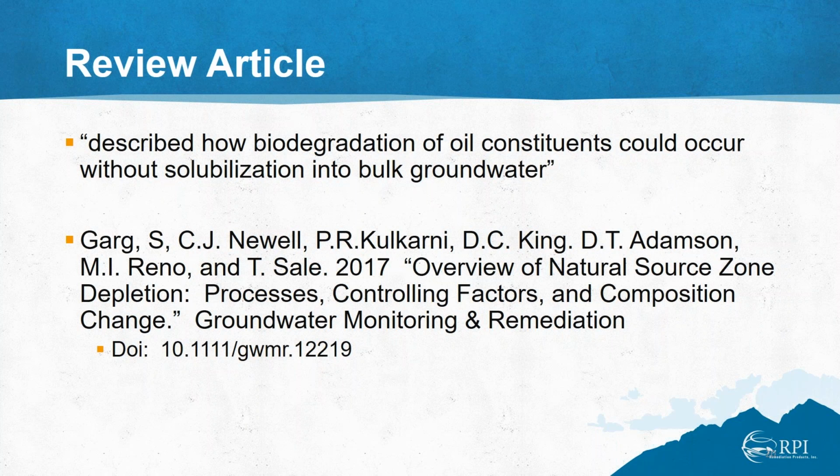We need to think about that in a different way, not in terms of an absorption property, but in terms of kinetics, the mass removal rate. And so if we can come up with a system that complements natural source zone depletion and the mechanisms that are in play to conduct that, and shorten the timeline for cleanup on sites from decades to years, then that has value. And that's what I'm suggesting.